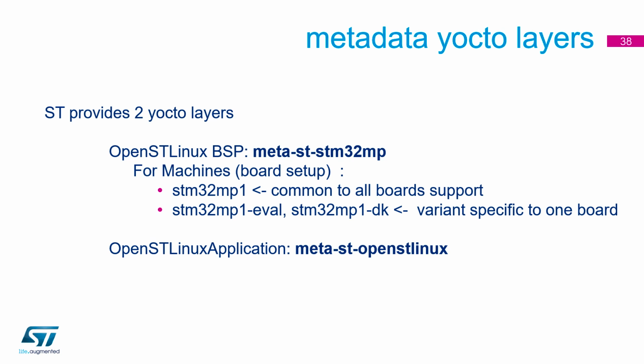So we're not going to tell you much about Yocto, but we provide two different Yocto layers. We've got one that supports all the different boards that we've got for the MP1s, and then we've got one that supports the actual device itself. So you've got the items that are common to all boards, the board support package, and then things that are specific to boards, like the eval has a bigger display, extra peripherals, and more connectors on it. And then you've got the actual Linux applications as well, so the OpenSTLinux applications. We've already provided all of these for the Yocto system, so if you've got your Yocto tools, it should be fairly straightforward for you to generate your distribution package.